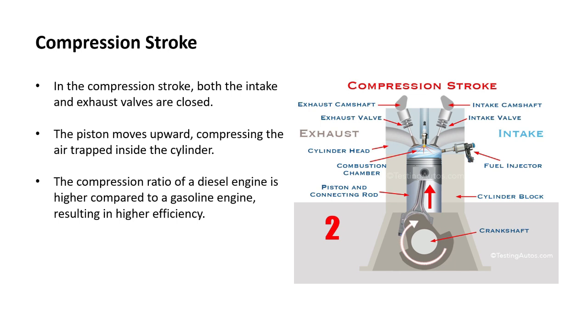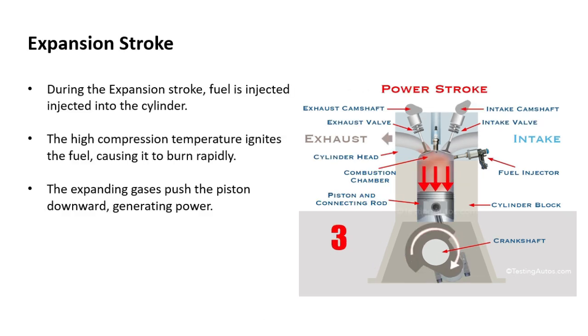As we compress the air still further, the temperature is going to rise to such a point that the fuel will ignite. Now, because we are compressing air in the second stroke, we refer to this stroke as a compression. So remember, we had suction, that is stroke 1, compression stroke 2, and now we are going on to stroke 3. Now we will see third stroke, that is expansion stroke.